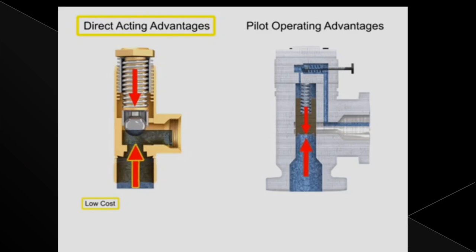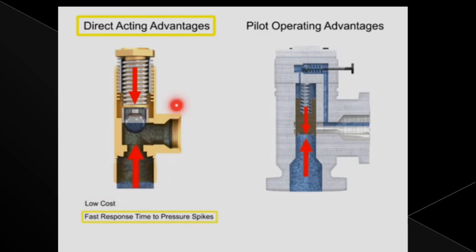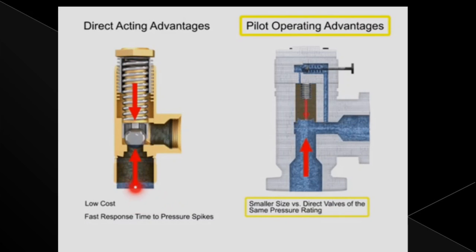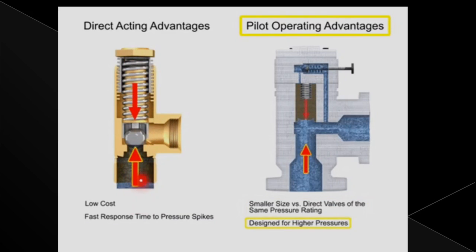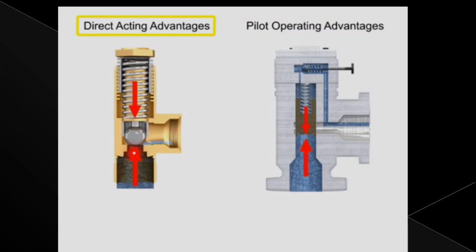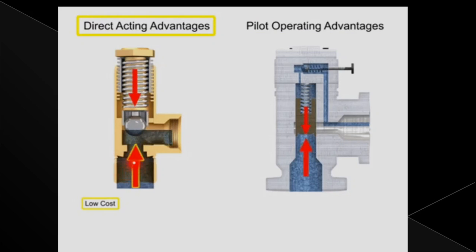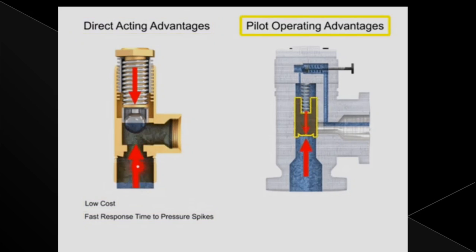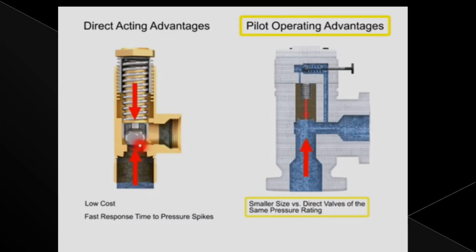So you can see this video. This is the simple pressure relief valve. This is the compound pressure relief valve. First we will see the simple pressure relief valve. What happens here? First there is a normally closed position. Liquid comes here, pressure increases, and it opens this ball valve. A small amount of liquid flows, and if the pressure increases still more, the complete valve opens and the flow takes place from here to here.